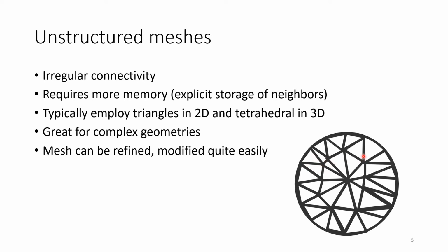Okay, so what you do is you store the coordinates of its elements. You store connectivity, so which element is connected with which. So that means I have more memory demands for my computer, which I need to solve, right? And so triangles are the most classical one because you can represent a lot of complex geometries with triangles.